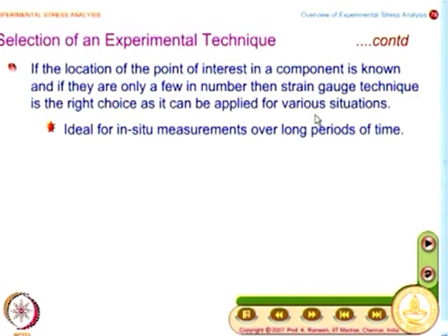In many instances, to identify the points you need, you may have to have a priori knowledge. If there is a failure, that indicates where you have to analyze more, and you can take some clue from brittle coatings and so on.